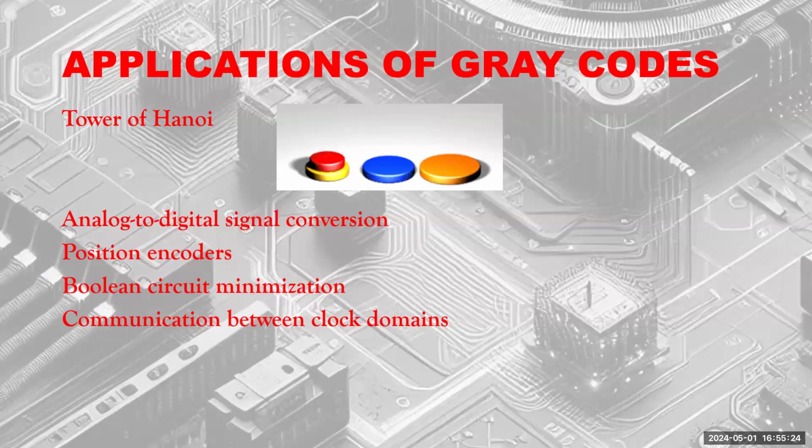So there is no glitch or intermediate output from any of the gates. They end up producing one clean next state transition with the lowest energy, and that way it will also work fastest through the next state discovery. So not only will you have a high performance circuit, you will have a low energy circuit. So it's a huge advantage to discover gray coding instead of binary or some other random number coding.